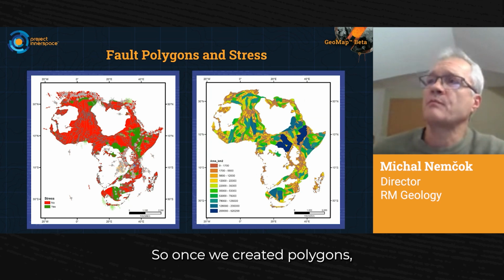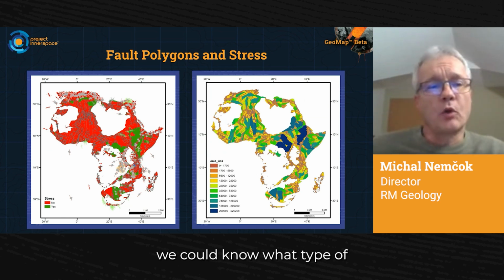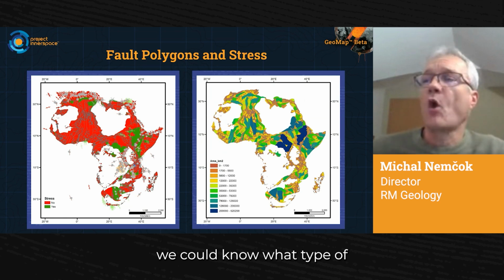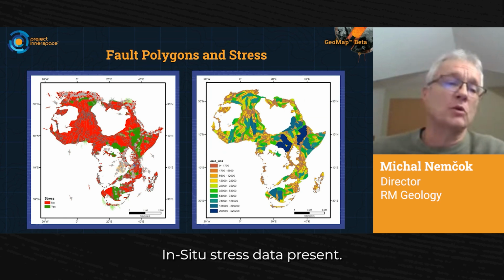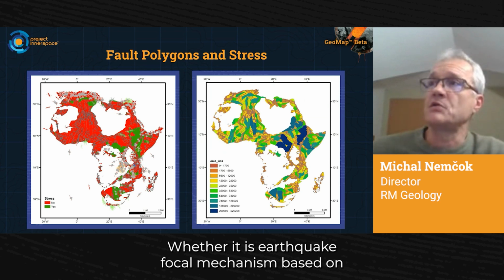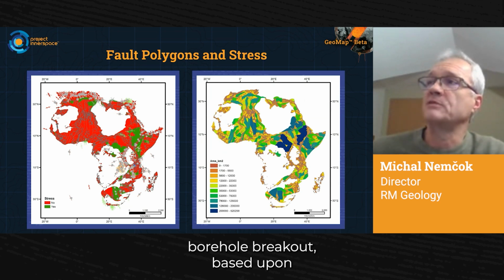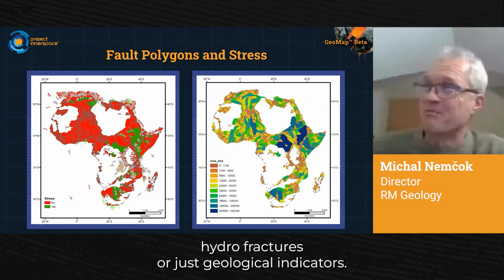So once we created polygons, we could know what type of stress datum characterizing in situ stress is present there, whether it's earthquake focal mechanism based, borehole breakout based, drilling induced fractures based, overcoring hydrofractures, or just geological indicators.